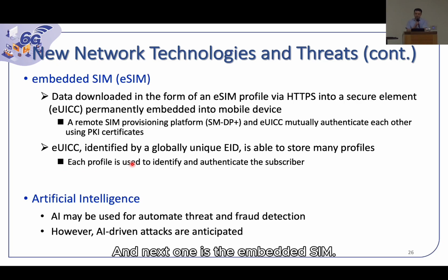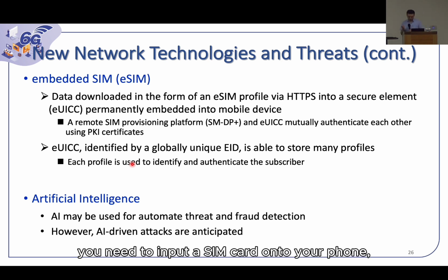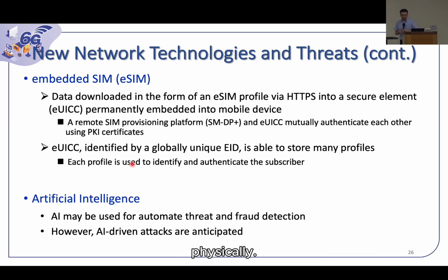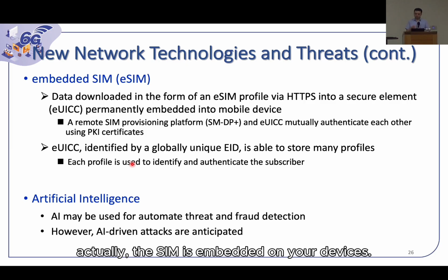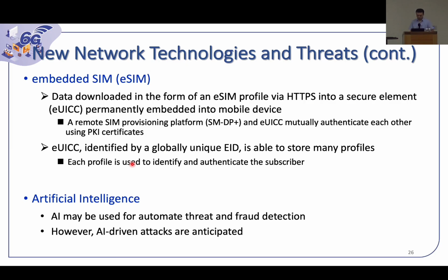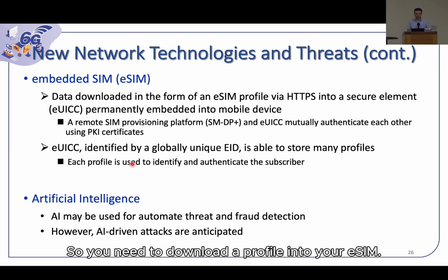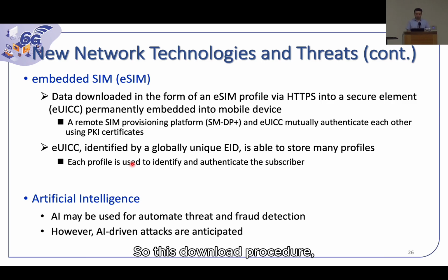And next one is the embedded SIM. So embedded SIM is a new feature. Actually, currently we already have it. Before, with a SIM card, you needed to insert a SIM card into your phone physically. But based on the eSIM, the SIM is embedded on your device. So you need to download a profile into your eSIM. This download procedure is based on the PKI